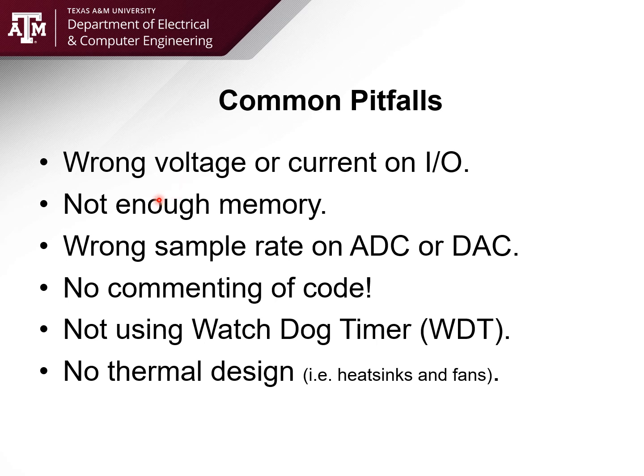Not having enough memory. This is very common as well. Not planning ahead and going, hey, I need probably X megabytes of memory or X kilobytes of memory on an embedded system, or even X gigabytes. Thinking ahead is very important here, and make sure you pick the right microcontroller for the right application.